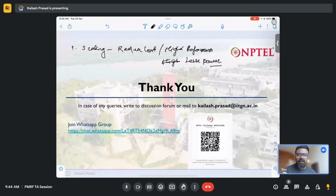And this is the basic idea behind shifting from one node to another node, right? When do you say that, okay, I'm shifting from one node to another, 5 nanometer to 3 nanometer? If you have a substantial performance benefit and power benefit. The thing is, why do we not go to a larger area? Because the area is the cost. You should understand that. The lesser the area, the lesser the cost of designing the chip, and you can pack in more functionality in the same area.